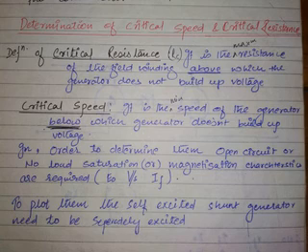So let us consider this with respect to time. When IF is 0, let there be a small residual flux. Due to the small residual flux, there is a small voltage, ER. What does this small voltage produce? It produces some IR, which means current flowing into the field winding. So this is field current only. This IR produces more flux because it is flowing into the field winding.